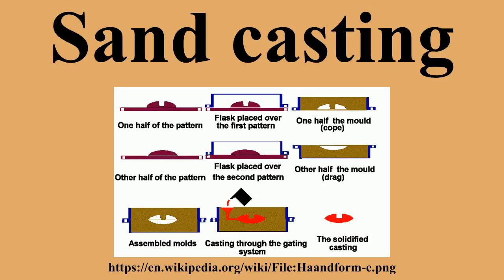This forms a green mold which must be dried to receive the hot metal. If the mold is not sufficiently dried, steam explosion can occur that can throw molten metal about. In some cases, the sand may be oiled instead of moistened, which makes casting possible without waiting for the sand to dry. Sand may also be bonded by chemical binders, such as furane resins or amine-hardened resins.